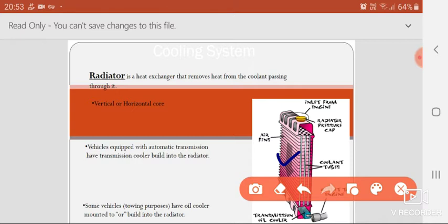And that is used in the radiator. The radiator is in front of you, you can see the air fins. Air fins, why? I told you, Q is equal to UA delta T. Q means heat transfer, A is surface area. Q is directly proportional to A. The heat transfer is directly proportional to surface area. By increasing the surface area, that is the air fins, we have increased the heat transfer. So the coolant loses more heat to the cooling air, or the air which passes through the fan. This is one part of this parameter.